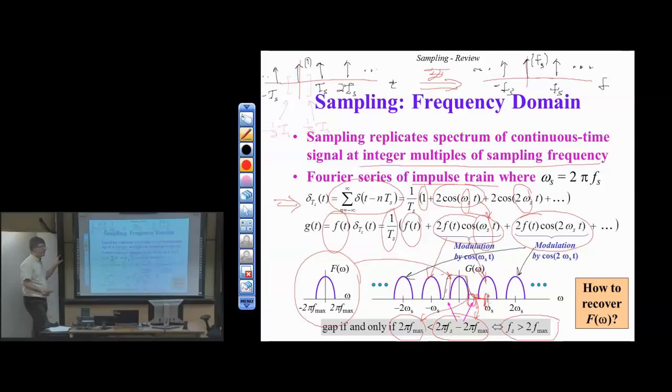It means I can capture up to 10 hertz. But now I have to figure out what kind of anti-aliasing low-pass filter I need. I might put the pass band at 9 hertz and the stop band at 9.9. So I'll lose a little bit of my signal that I want. I'll shave off a hertz of my signal, but at least I don't get aliasing much. I reduce the amount of aliasing. Yes, we do that.